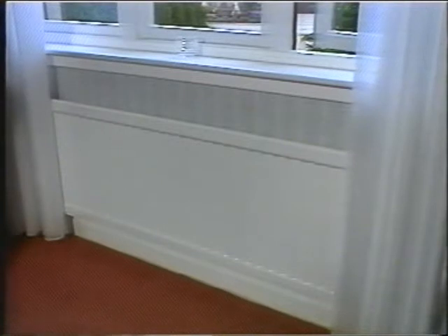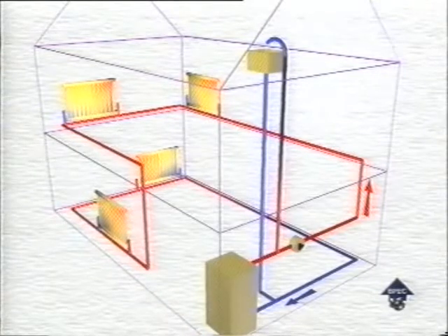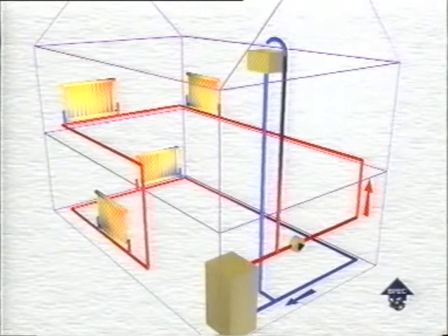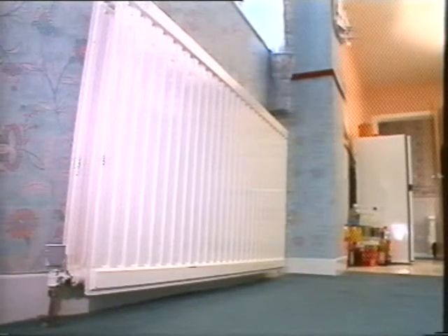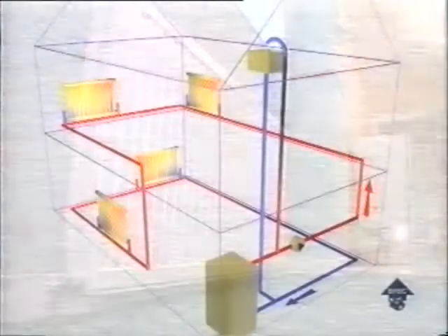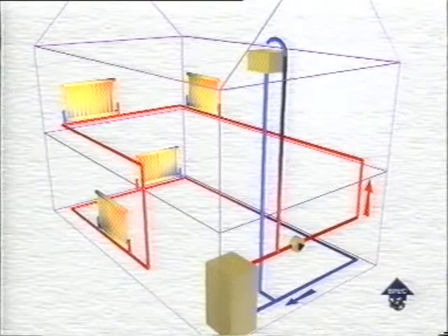As well as choosing the appropriate system, we also need to decide on the pipe circuit. Again, there are several types. Here, there's a single loop of pipe. It's usually 22 millimeters in diameter with 15 millimeter tails to and from the radiators. It's easy to install, but there are obvious problems of balance because the first radiator on the loop will be hotter than the last one. This means having to fit larger radiators at the end of the circuit. Because of these problems, this type of system is no longer installed.